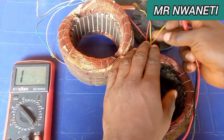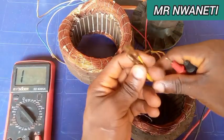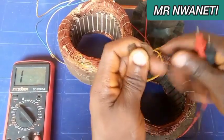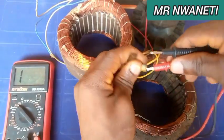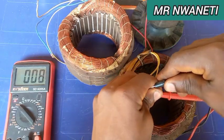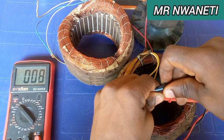Now let me check the ohms resistance of this exciter terminal. The resistance is 8 ohms.